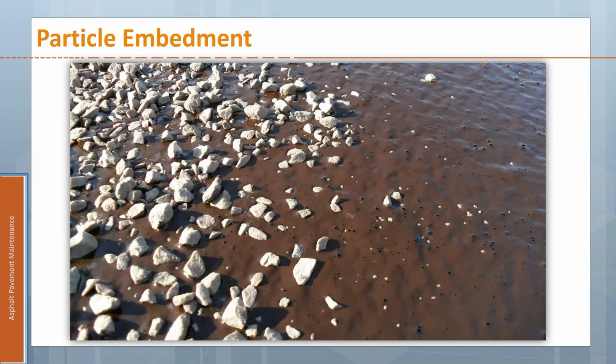We want it to get in there, we're going to mash it down with the roller, and we want it to stay stuck in there. But when the aggregates are all covering the emulsion, we're not really going to see the oil. Okay? It's going to be underneath. That's just the glue between the surface that we see and that underlying material.